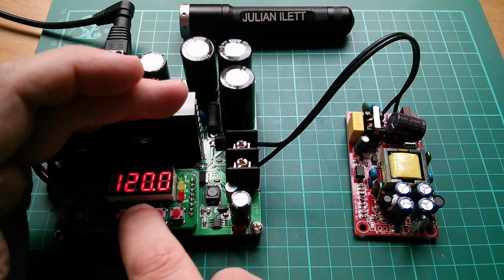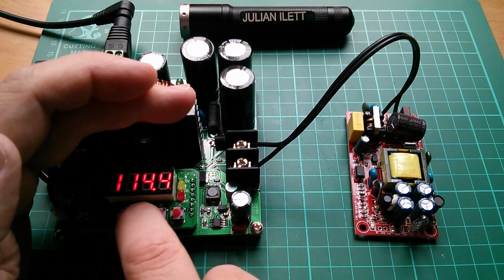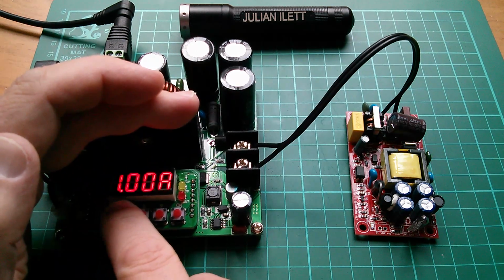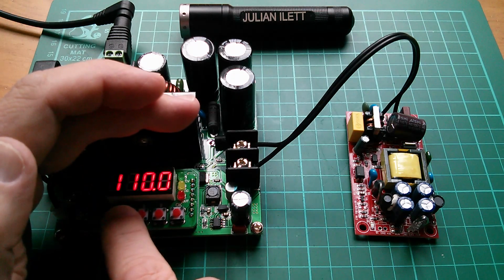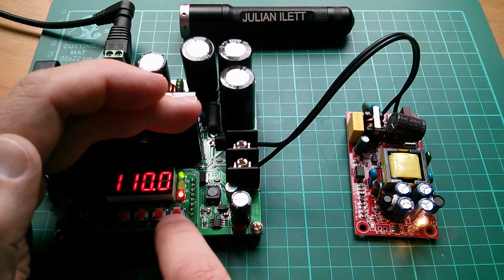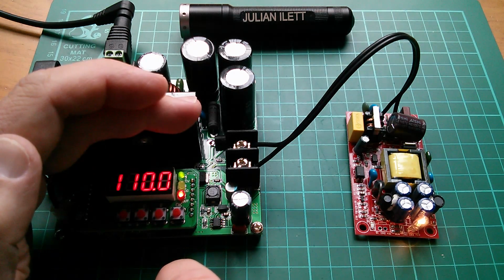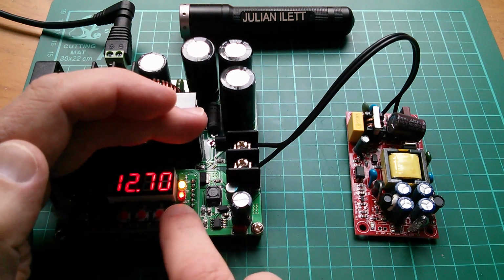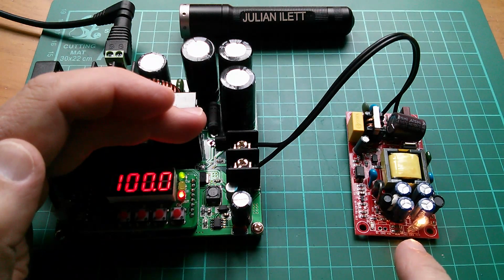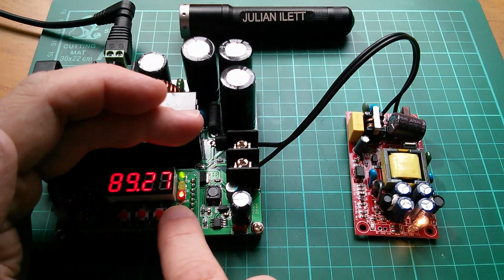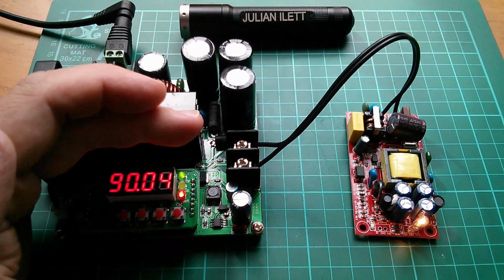So let's take it down to 110, which was the minimum it says it can operate on. So 110, 1 amp again. That's not a very sensible current limit, but let's give it a try. 110 volts. Now I think that came on at somewhere below 110 volts. So let's keep trying it and taking the voltage down. Okay, let's try it at 100 volts. Yeah, that works. The 12 volt output has come on. Okay, let's try 90 volts. Yeah, that's come on. Well, I'm just going to keep going down.